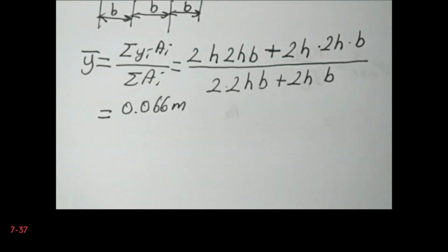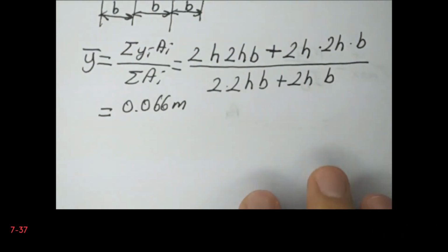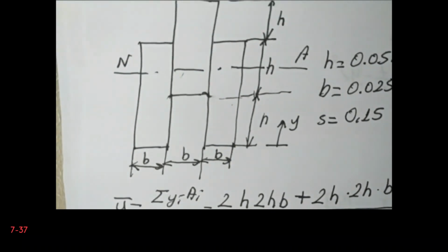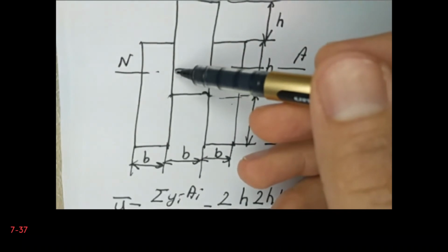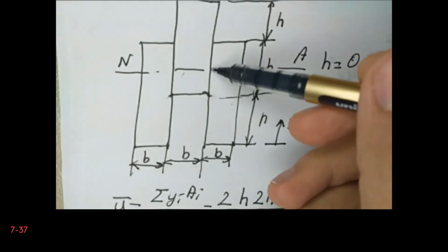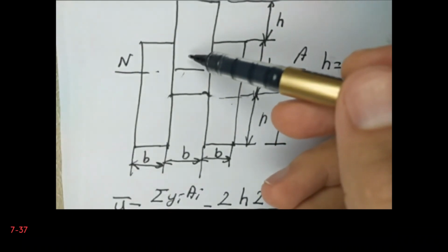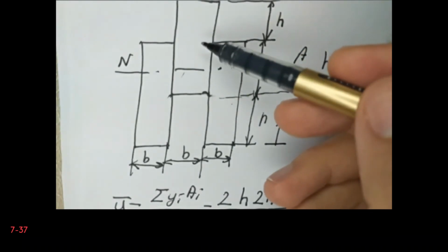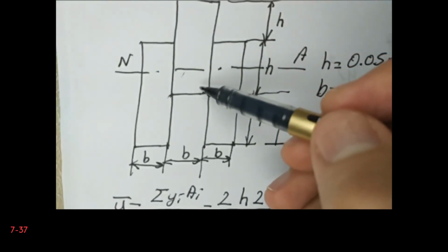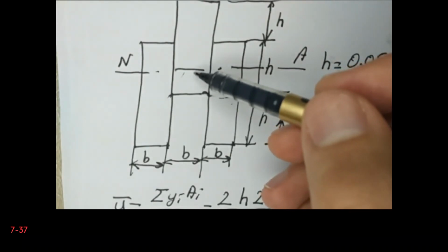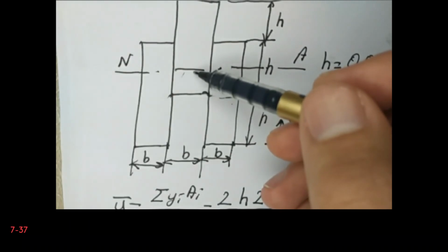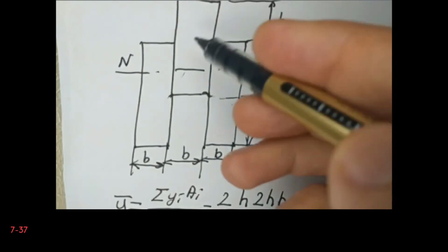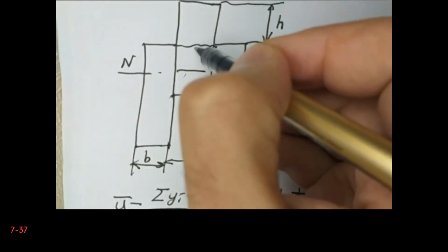Now we need to calculate, first, we are asked for the maximum force. So in fact then we can consider that the whole cross section is made of perfectly bonded material, and therefore we know that the formula of the shear stress solely depends on the first moment of the area divided by the thickness. In fact, this basically means that we see the maximum stress at a point where this ratio is maximum. So the first moment of the area divided by the thickness. In fact, thickness is minimum here, and so the area is larger,